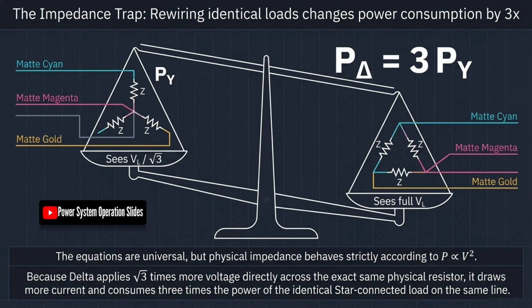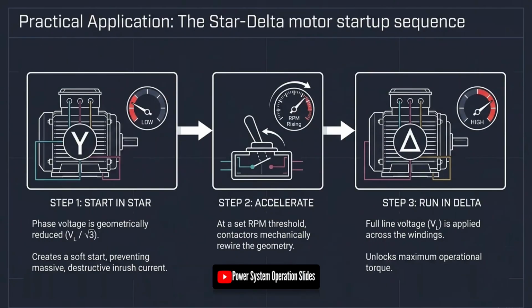The delta connection has a different physical and electrical arrangement. In a delta configuration, the three windings are connected end-to-end to form a closed triangular loop. There is no common neutral point in the conventional delta arrangement, and the external system normally uses three conductors. The electrical relationships in delta are essentially the reverse of those in star.